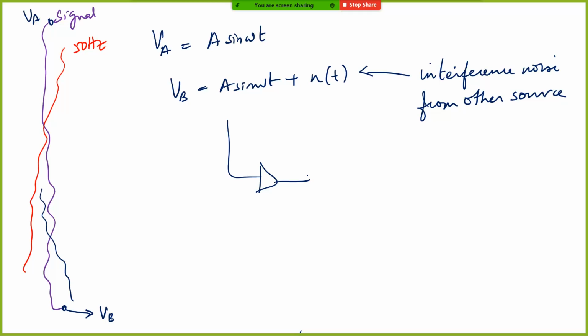Sometimes you might have noticed that if you have some sound system, public address system or some mic, and you bring your mobile phone near it, you'll hear that beep beep sound coming from your speakers, right? That is because of the interference caused by your mobile phone on the audio line. Some mixing happens, and some low frequency component gets added to your audio signal, and that becomes a big interferer.